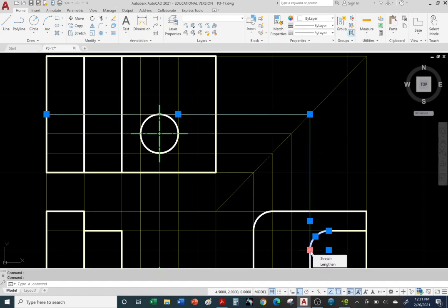So from this tangent point of the arc to the line, we're going to go straight up, hit the 45, go across, and we know that we're supposed to remove this bottom portion. So the line goes from here to here, right? Again, we project upward, hit the 45. So this is the 45, and we go across.